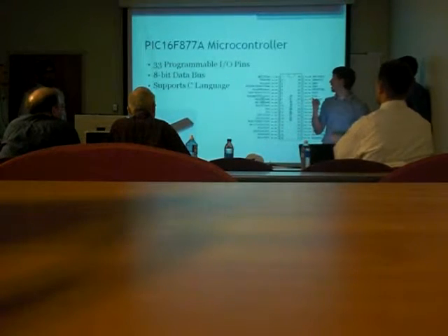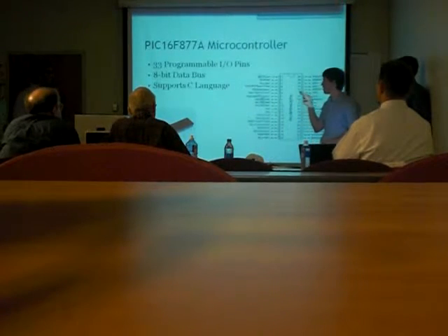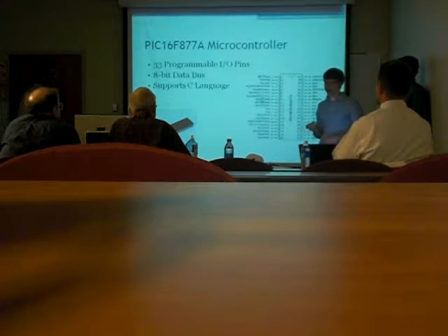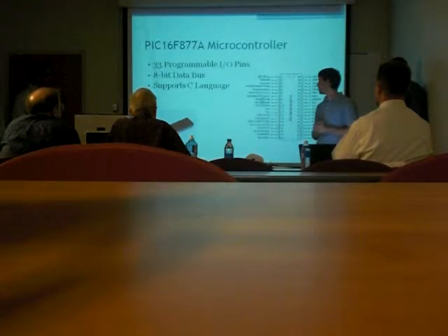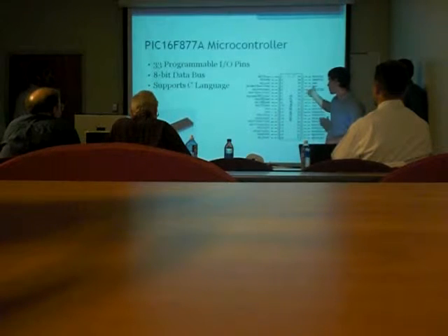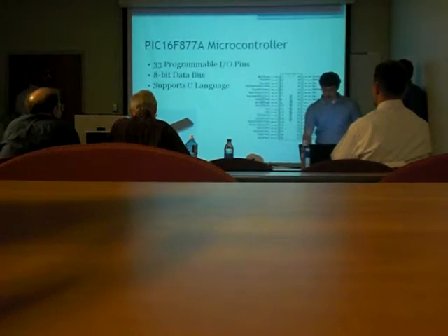On our first proposal, we were going with a PIC that was actually 18 pins, and that was when I thought we'd only need 12 input-outputs, but we had to upgrade to the PIC 16F877A. This one supports the C language, has the 8-bit data bus we needed, and 33 programmable input-output pins, which is more than enough to cover everything that we have to do.